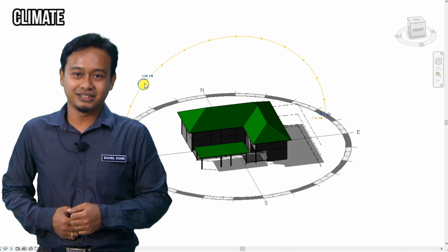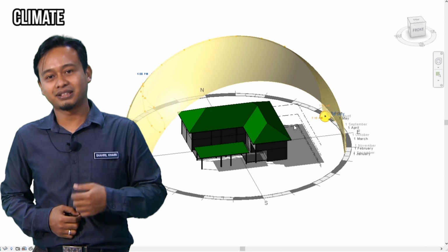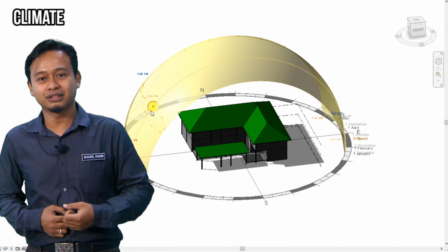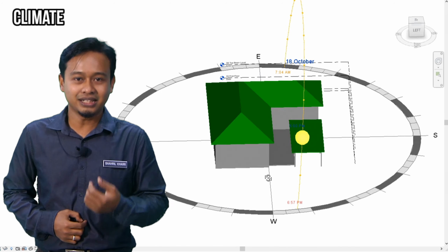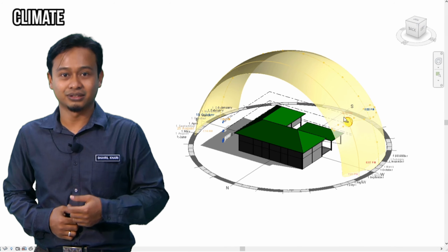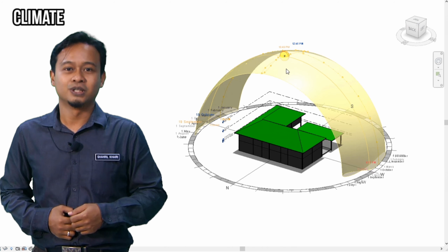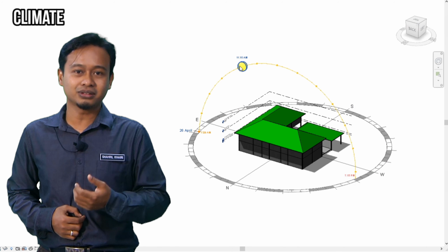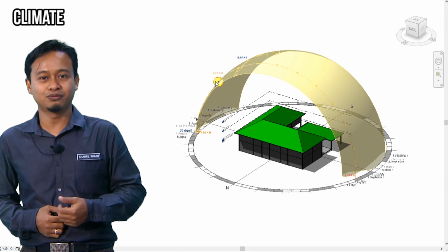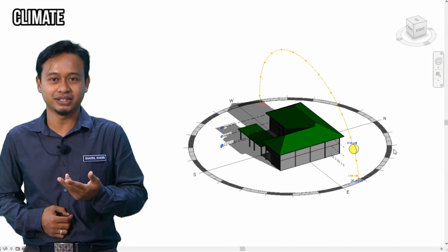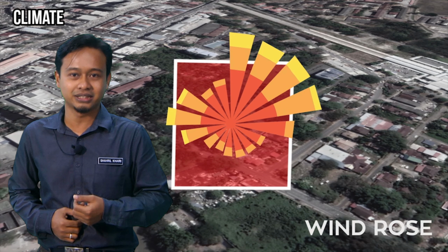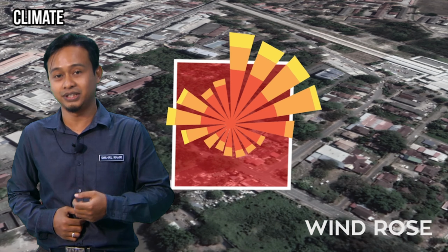One of the interesting items in site analysis is climate factors, which relate to the weather, site's orientation, solar path, solar gain and shadow. Best practice is to gather all climatic information such as rainfall, precipitation, temperature and wind, all considered during different times of the year.